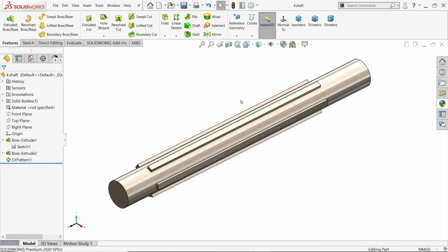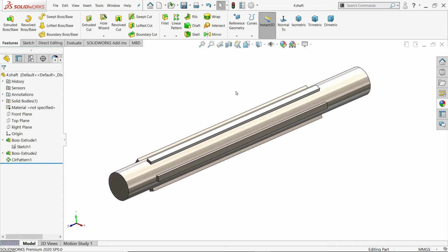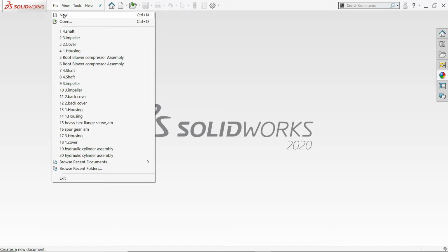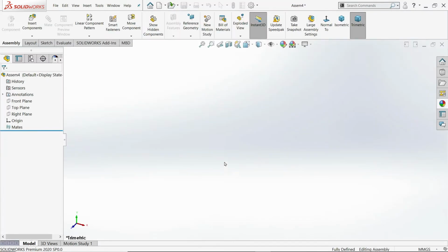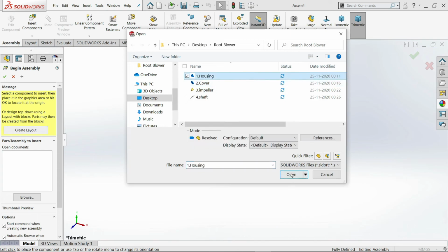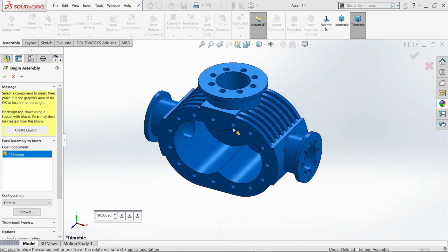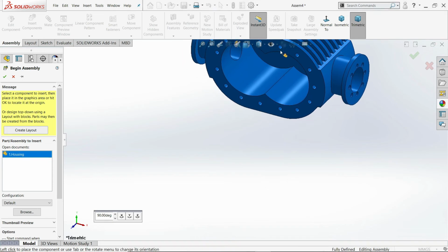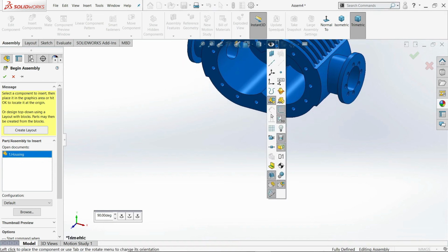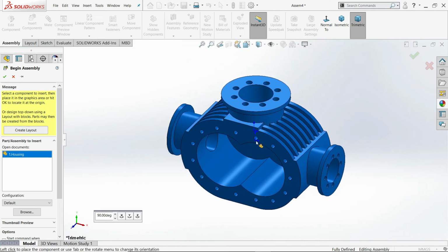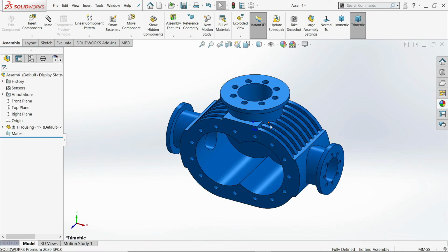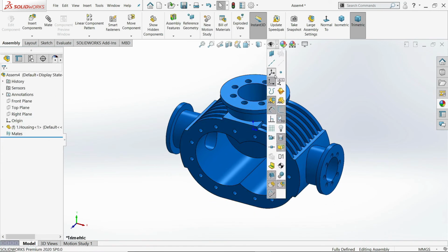Gear and bolt we will take from design library. So let's start assembly. Now here open new assembly. Okay, now first part I'll choose, just drag and show coordinate system, view origin, and connect to this point so that our geometry is located perfectly on center. Hide it.